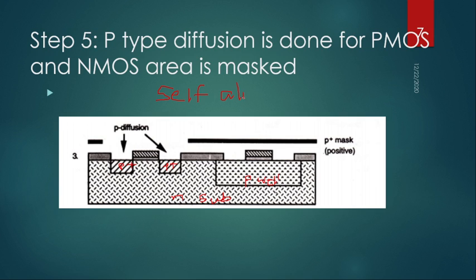process. The self-aligned process is used while doping the impurities, because the window between the terminals is very small, so you cannot adjust the impurities manually. These impurities get aligned by that process, and as P plus impurities are only required for fabricating PMOS, not for NMOS, this N region gets masked.